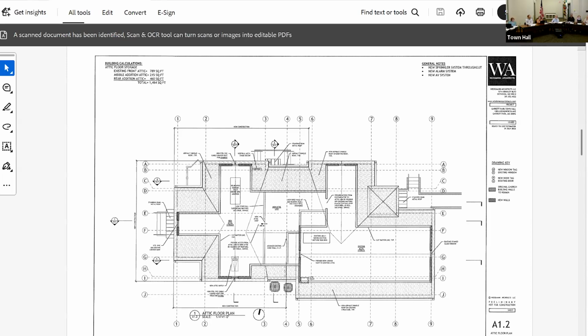So I guess that would preclude using a styrofoam panel type insulation on the outside, underneath the siding? A rigid insulation? Yes, that would have a lot of detailing consequences at the trims of the windows and extensions, although from an energy point of view, the continuous insulation would be a good idea. I would say, in order to keep the character of the building without adding another inch or more, you would insulate the cavity. Okay, thanks.